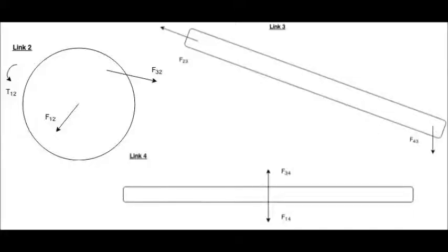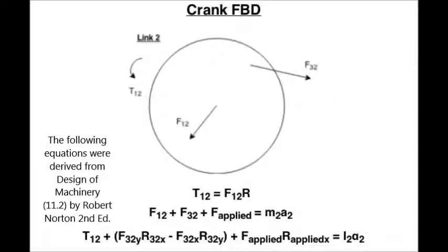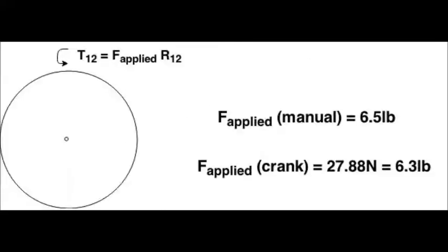With dynamic force analysis, our main concern is how much input force is needed to turn the crank at the handle. After taking the information provided by the results from our kinematic analysis, that is, the positions, velocities, and accelerations, as well as masses and mass moments of inertia of each component in the system, a matrix equation is compiled to solve all unknown values in the system. To simplify calculations, it is assumed that all links are rigid and joints and pins are frictionless.